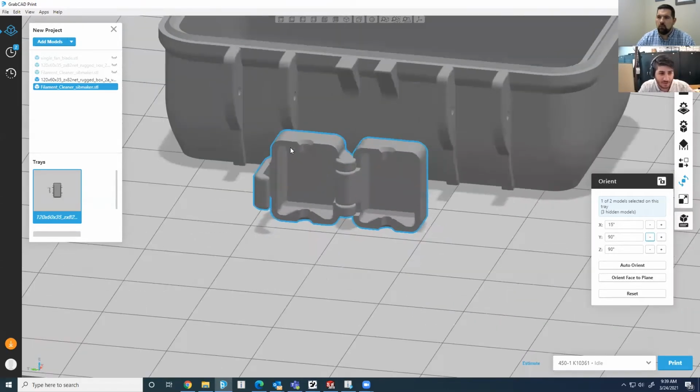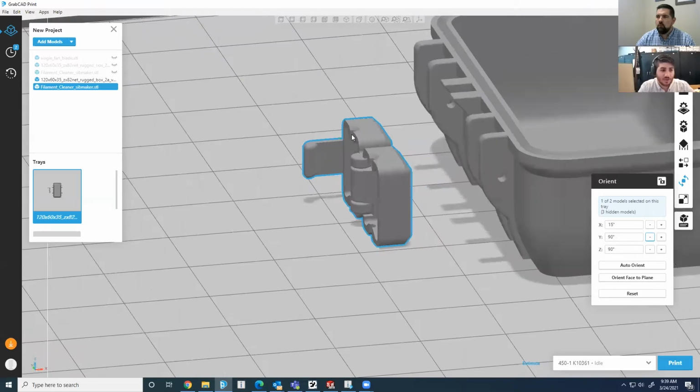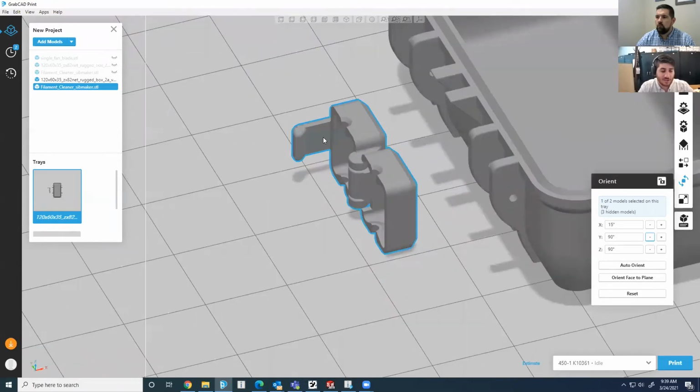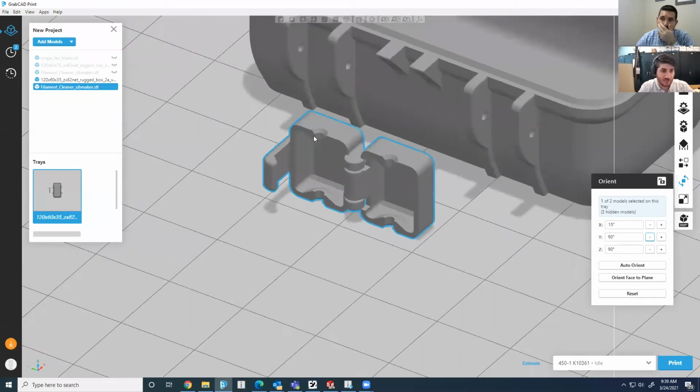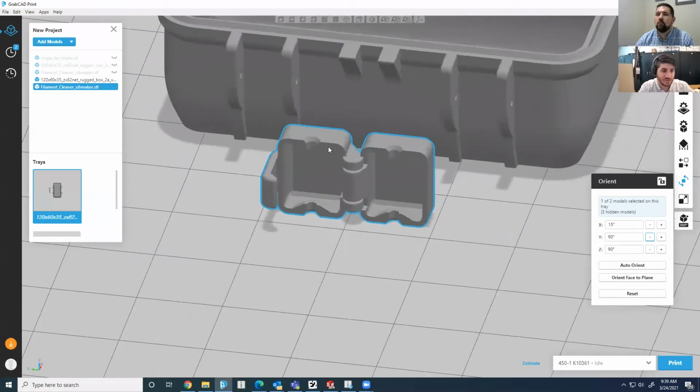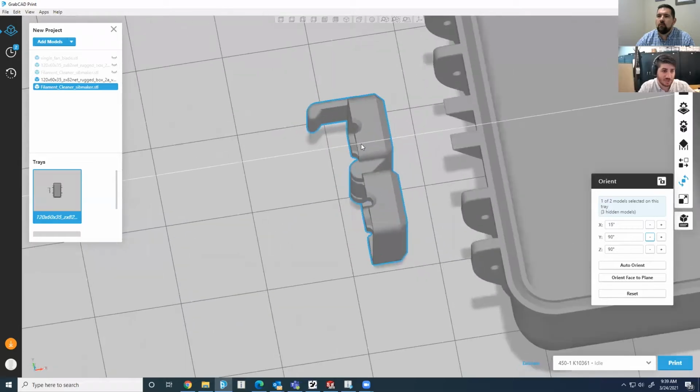That way you have the layer line going with the contour of the part, so that it has its ability to bend as well as look really nice, so that you don't have what's called stepping, where the machine moves up its layer height and you'll start to notice stepping. So it looks like a staircase going up that part if it was to be built like that in the build tray.